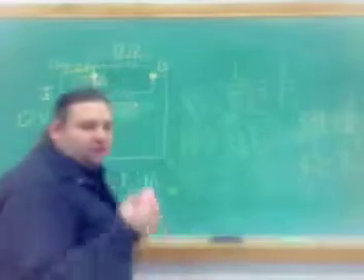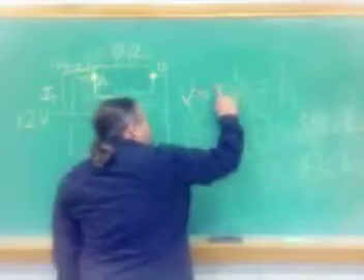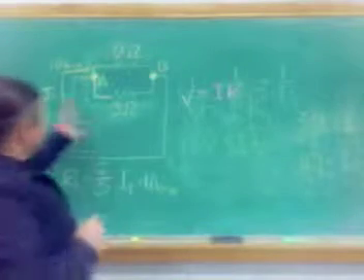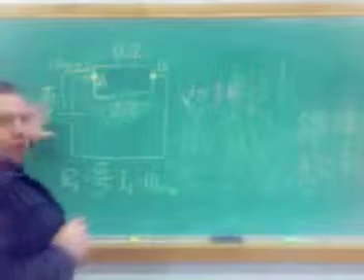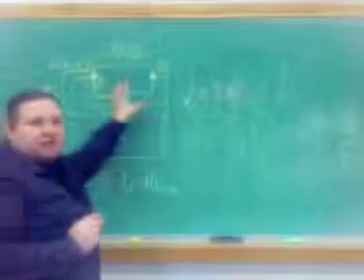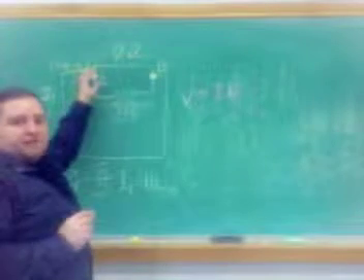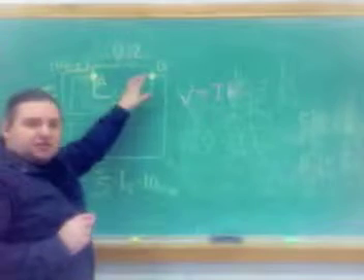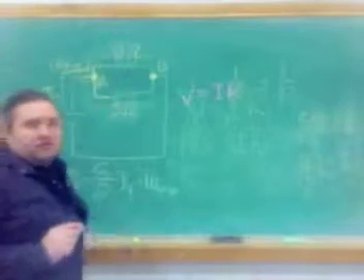Okay? So, I'm going to use red now. I get V is equal to IR. Okay? Voltage across each one of these resistors, it's still the 12 volts. All of it has to be consumed, and these two resistors are going to consume it. So the potential drop from here to here is 12 volts. So that's how much potential drop that voltage that resistor experiences and that resistor experiences.